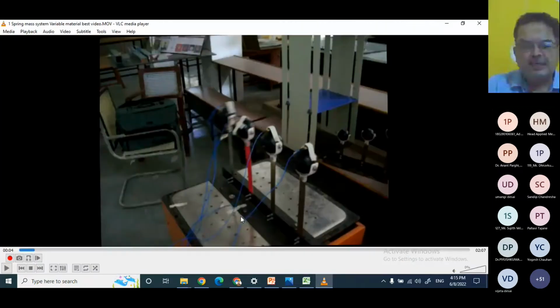So here you can see these are the four models placed on the shake table. The same motion is applied. Now we know that the frequency of all the four is different, right? And we have already calculated the frequency of all the four models theoretically. So we know which model is stiff and which model is flexible, right? Initially we knew this, and then we fabricated them.